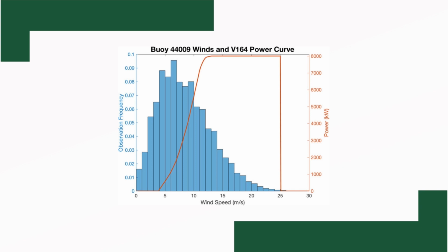It provides a quantitative and statistical basis for evaluating the reliability, variability and energy production potential of wind resource at a specific location. One of the most common distributions is the Weibull distribution, which is used in the wind energy sector.